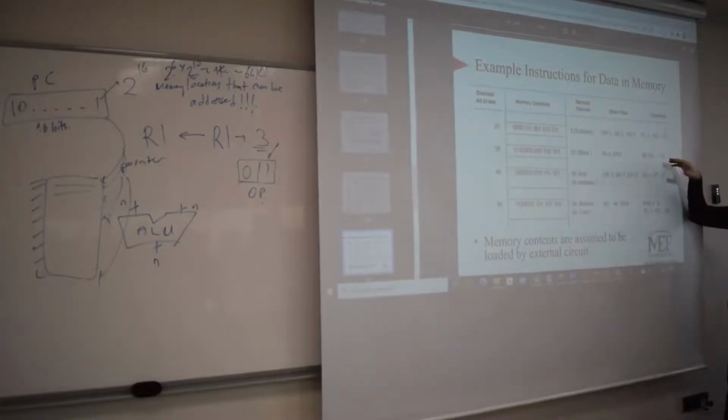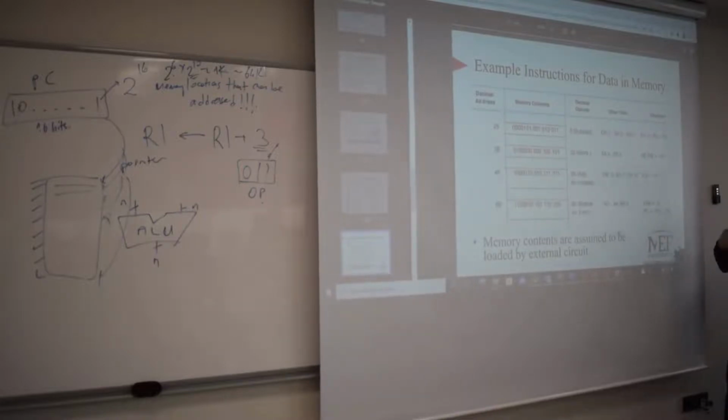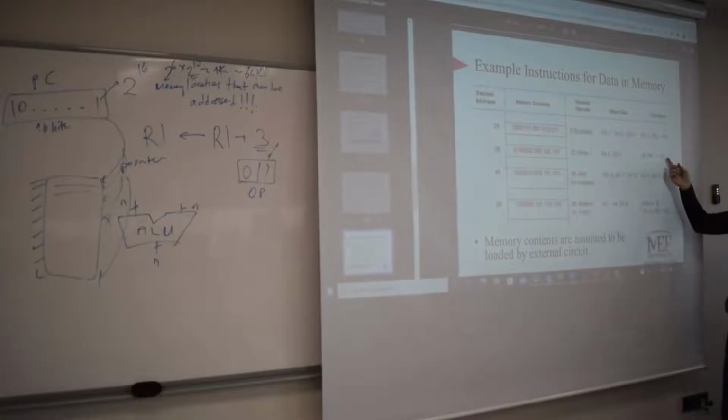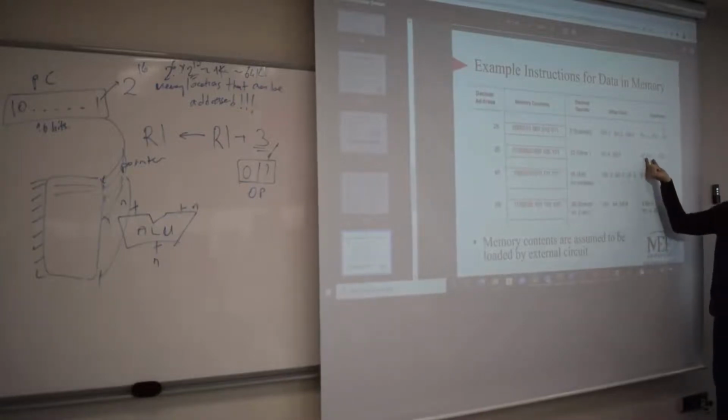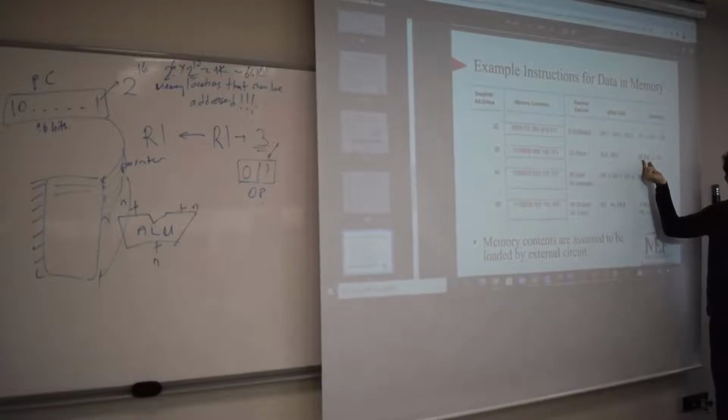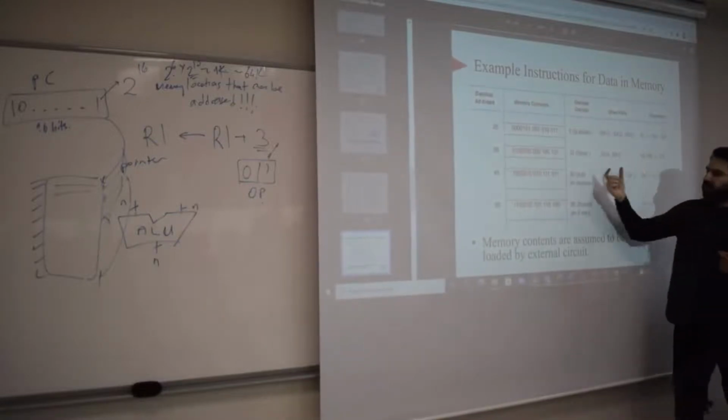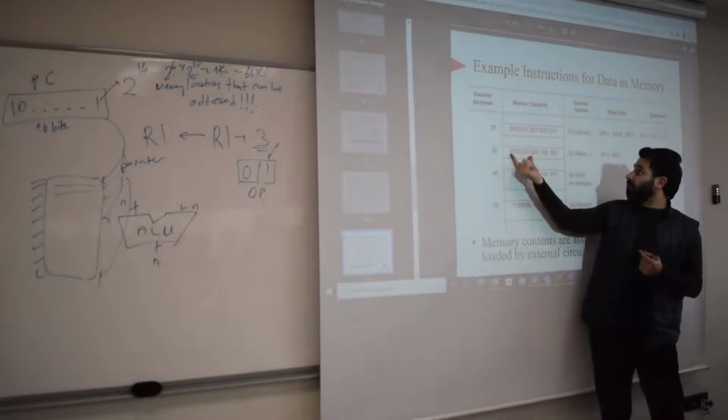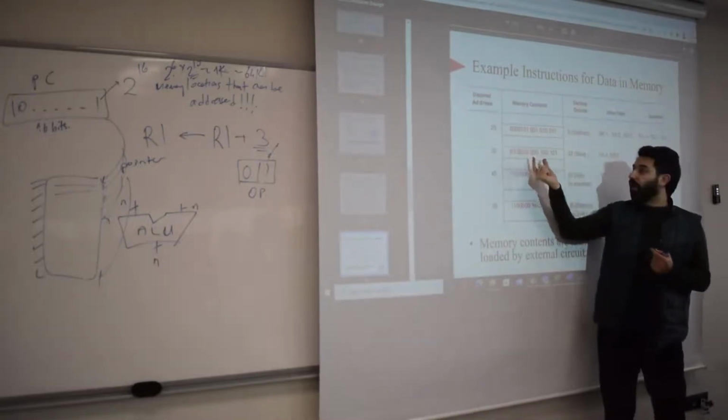So here, the question is about storing information. All you have to do, R5 is the data that you want to write to memory. That's the R5 content. Then you write to where? The address that is stored in R4. Okay? So therefore, this is a memory write, or store information.